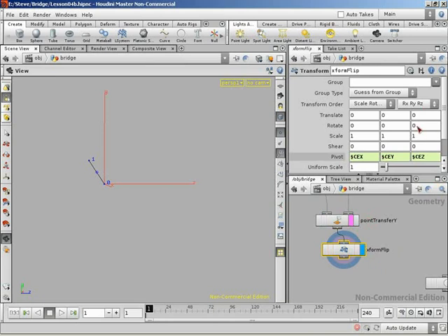So, yeah, it's basically the center. We can see the pivot here. It's now at the center. Now the center of our line. Which will work for scaling negatively. Yeah, so if we scale negatively based on the center, we're going to basically flip this guy over so that they cross at the center. So we can take our scale in Z and set that to -1. Very nice. So now we've got a crisscross, which we can wire these two guys down into a merge.